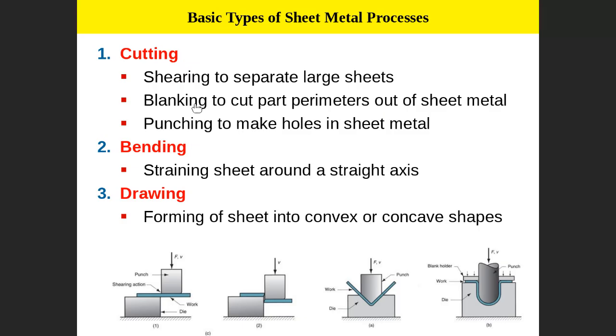The items that we are going to cover here are cutting, bending, and drawing. This is sheet metal working. Cutting here means to separate the sheet in two. Someone might say you told us this is deformation and no cutting. Yes, I agree with you. So why do you say cutting here? Actually, this cutting is not to cut to shape, but to prepare the sheet for the deformation.